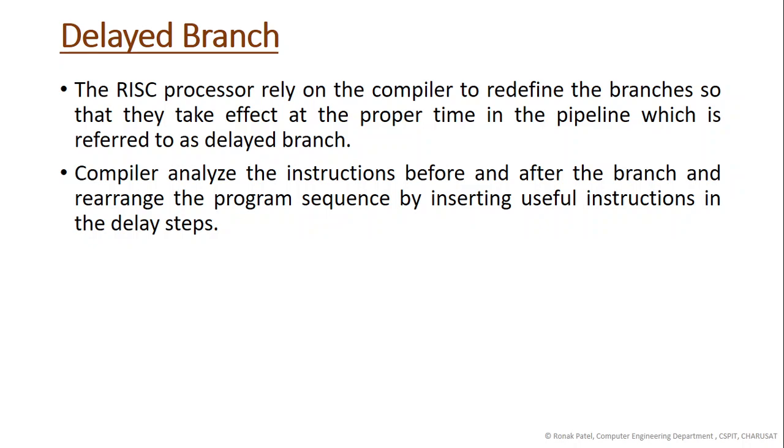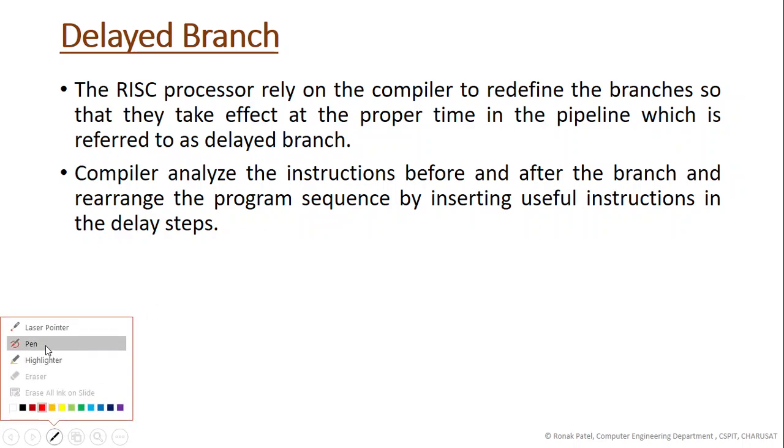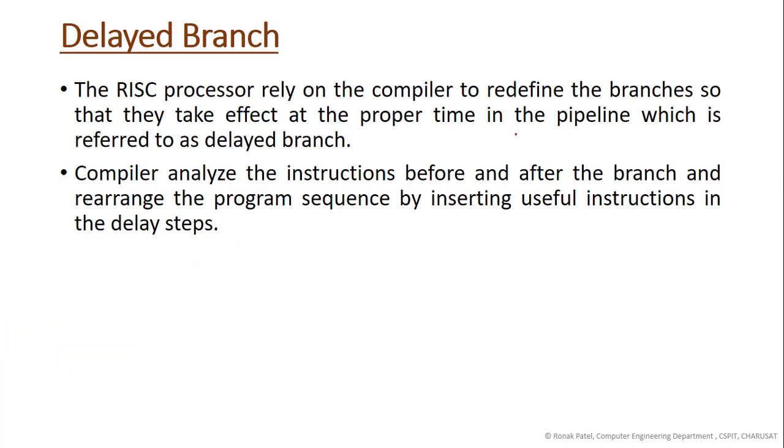The next is delayed branch. The RISC processor relies on the compiler to redefine the branches so that they take effect at the proper time in the pipeline, which is referred to as a delayed branch, right? So what it says is, it redefines the branches.